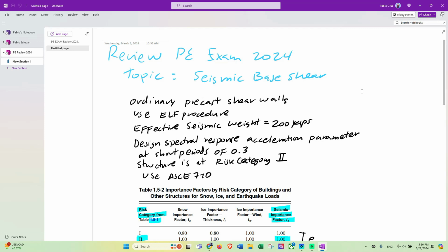The topic: seismic base shear. We are making a selective review of some topics for the PE exam. So in this case, we are talking about an ordinary precast shear wall building, and we're gonna be using the equivalent lateral force (ELF) procedure.